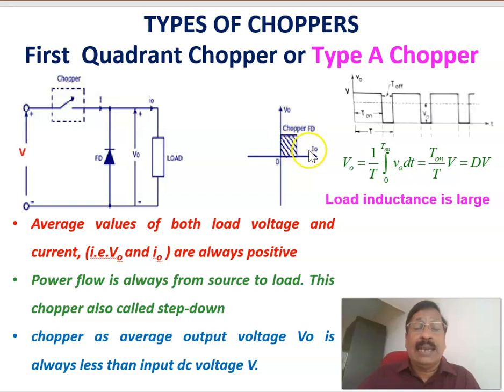Now we can say that this current is proportional to a mechanical quantity, torque, and this is the speed, which is proportional to the voltage. Therefore, this is a torque axis in the mechanical plane, here torque as well as omega m. Here, the product of electrical quantities V0 and I0 is positive. Therefore, that is a motoring operation.